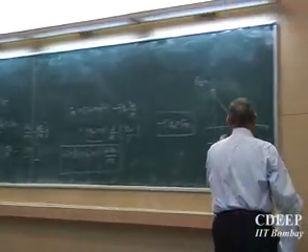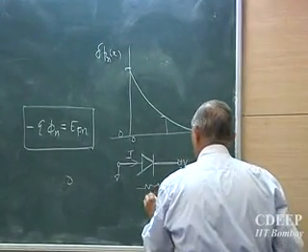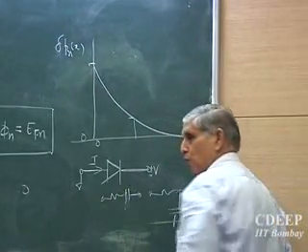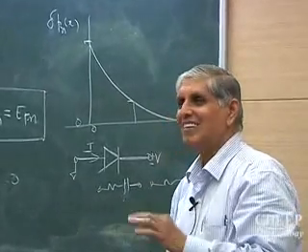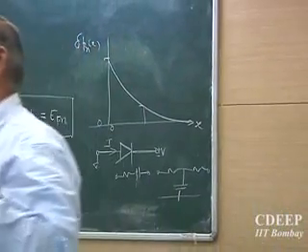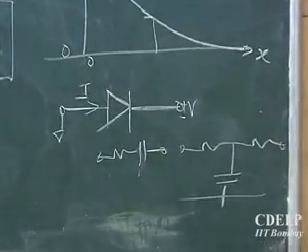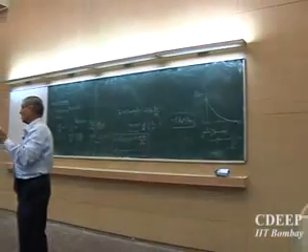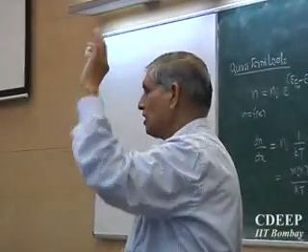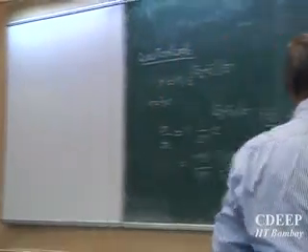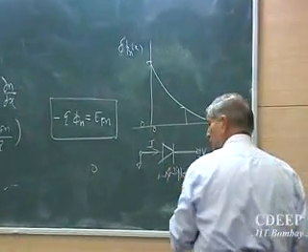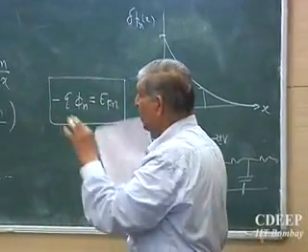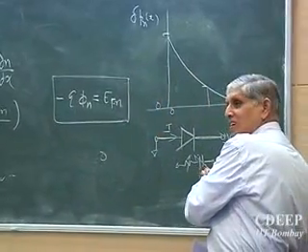Once we do this, in a circuit I cannot always use this, so I would like to connect this relationship. I don't know what kind of equivalence I can create for a diode. I don't want to say right now which one. Some kind of equivalent circuit I would like to create at the end, because the circuit person doesn't care about the device physics, only equivalent RCs. If I can create at the end of the day for any device its equivalent, then in a circuit I replace that device by that equivalent and solve the network normally. So ultimately, to get this equivalence, how much this will be varying or not varying, I would like to know, and to do this, I'll use this. Is that clear? So I keep showing you this connection, otherwise you should not feel I am so keen to do only device physics. No, ultimately I am only looking for my circuit.